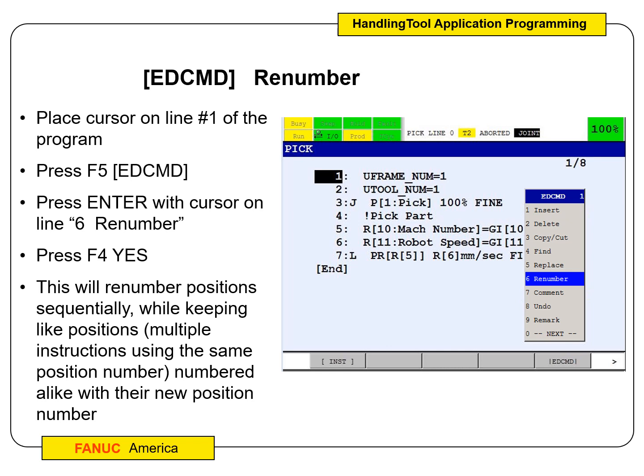Okay, renumber. We'll renumber your positions, not your position registers in a program. So move to the top of the program, say renumber, and it'll say, do you want to do that? And it will renumber all your P's, not your PRs. Again, it doesn't change anything other than what's being displayed. Your positions don't do. The program's going to be the same.